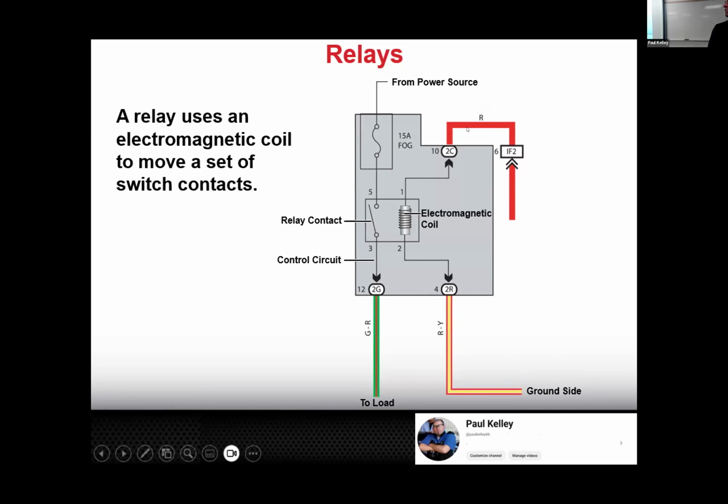It's saying we have 12 volts coming in, going to 1. And then if we look, 2 goes out and it goes to the ground. Now where's the switch? In this example, I didn't give it. We could have a switch on the 12 volt side. And yes, if we close the switch, now 12 volts hits the coil, which would mean ground it would have all the time, right? Or we could have 12 volts all the time and we could have the switch on the ground side. The switch can give 12 volts or the switch can give ground. If it gives 12 volts, that means this has ground all the time. If it gives ground, that means it has 12 volts all the time. In this case, I didn't give you that information.